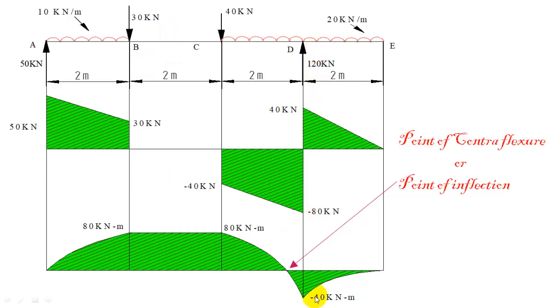Now at D we got the bending moment as minus 40 and also we know that variation of bending moment is parabolic. From 80 to minus 40 it has to vary parabolically, once again without a peak. There is no peak because shear force is not changing its sign. It's negative from left hand to right hand. There is no change of sign. Always the shear force is negative only. So without a peak, no peak here, so continuously going down and it's reaching minus 40. Continuously the bending moment is decreasing to minus 40.